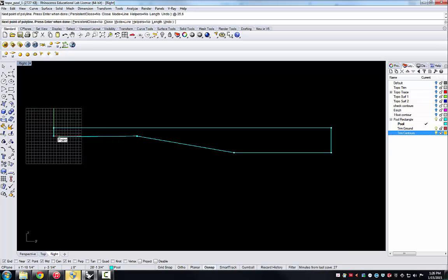So now I can close this polyline by going back to the origin with a 3-foot level on the left and a 9-foot level to the right and a sloping section in the middle. This is a nice single piece of geometry that we can now do some minor editing to.